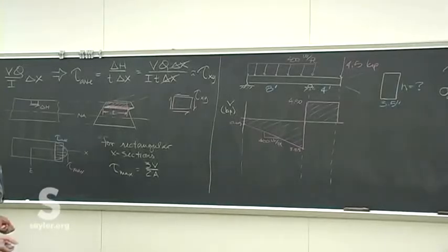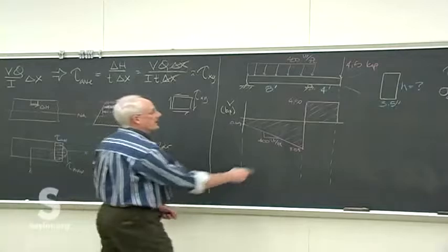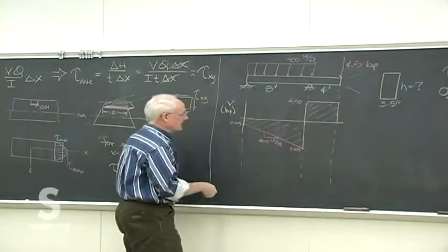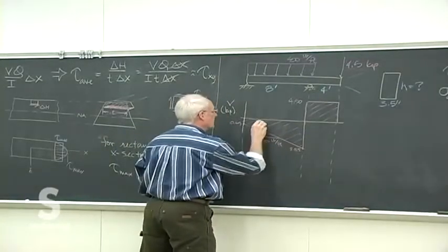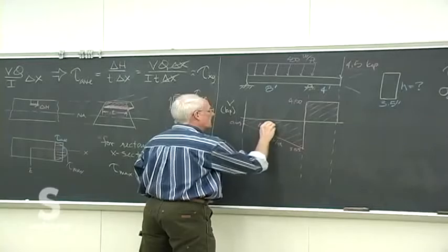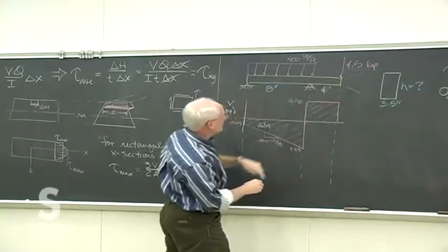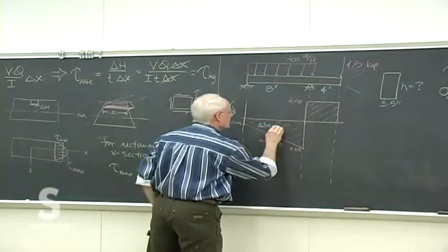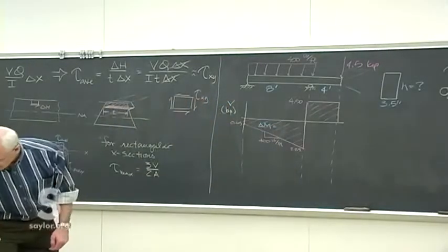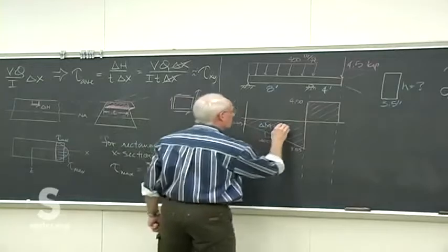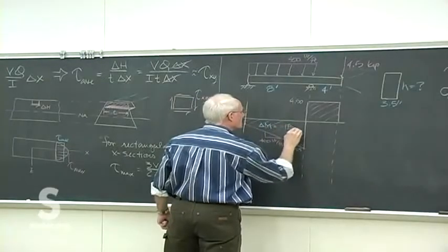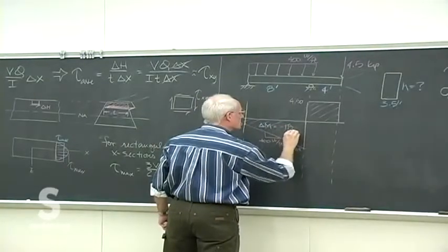In terms of the maximum moment, all we need to really worry about is what are those areas, because remember that's delta M, and we have 0 moment here because that's pinned, we have 0 moment there because that's free, so whichever one of these is the greatest delta moment will be the worst case thing.